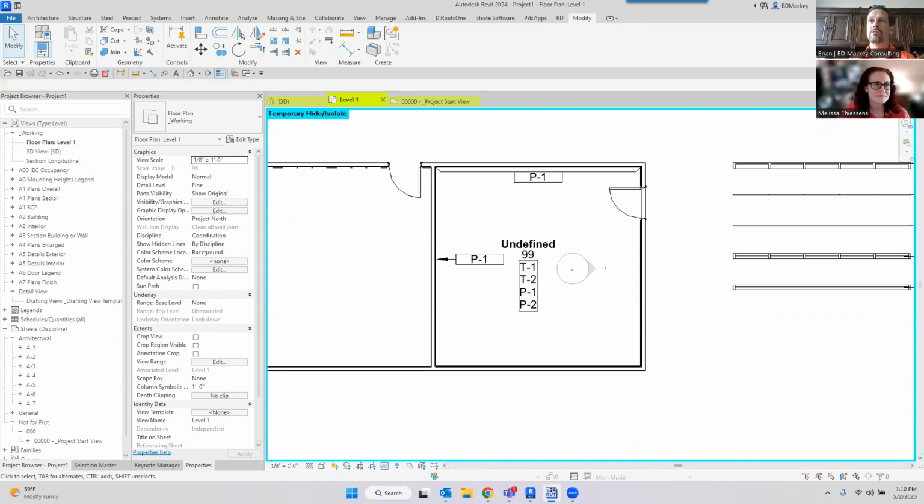Don't ever use a stacked wall. The biggest disadvantage of a stacked wall is you cannot control the connectivity, the joins to other walls when they come into play. I had one client that did a stacked wall where they wanted it to be modeled perfectly. So every time there was a bump out in the brick, they modeled it as a 6-inch tall stacked wall. They had a brick with a 2-inch air gap and another brick with a 2 3/4 inch air gap, and they stacked it all the way up the building. So the stacked wall was made up of like 30 stacks.